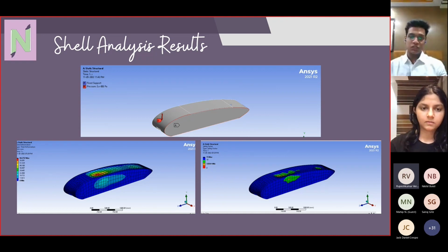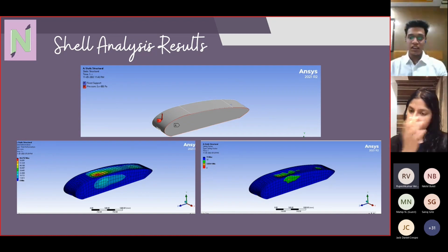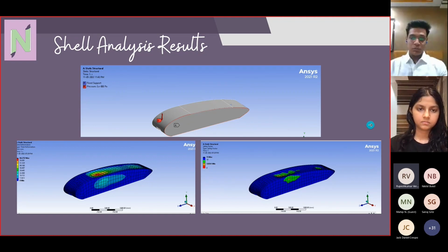The CAD of the shell was imported with mechanical properties typical of carbon fiber and epoxy bidirectional composite, which we'll be using for the manufacturing, with a 45/0/45 configuration. And loading conditions were assigned as per the CFD simulation results at the speed of 200 kmph. In the manufacturing process, we'll be making a negative mold using CNC routing, and then further we'll lay up carbon fiber with 45/0/45 orientations before vacuum bagging it.